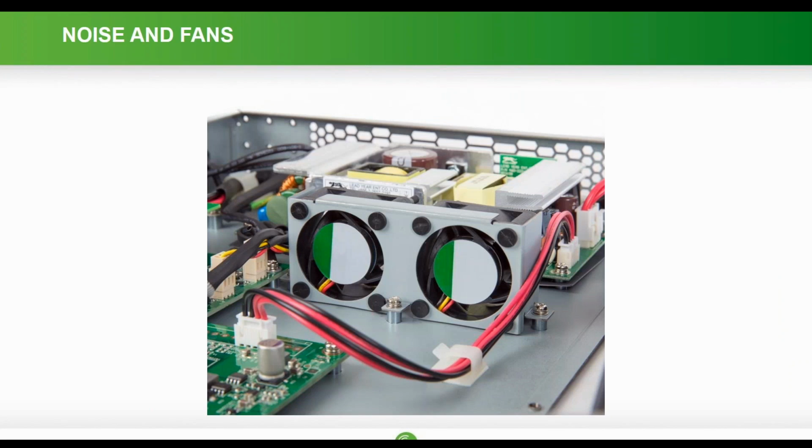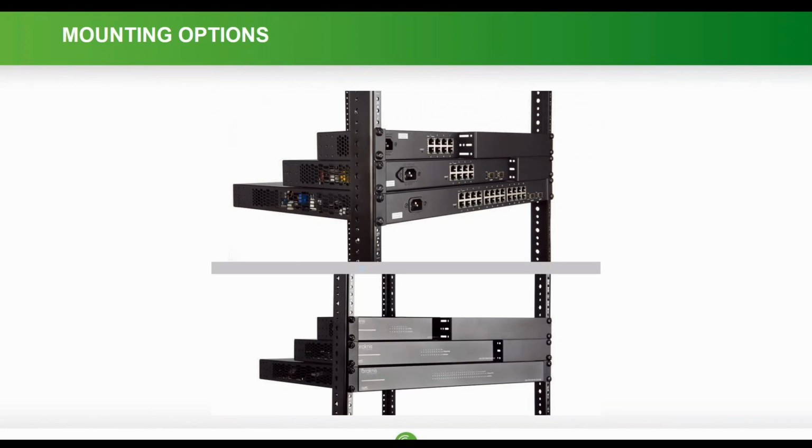The other thing you see in the PoE models is in terms of fans. For the 300 series, those were multiple or variable speed fans controlled by wattage, so how many watts the switch is supplying controls what speed the fans run. We recognize that this is not the most efficient way to do it, so with the new line of switches, we have temperature controlled speed fans. There's a thermal sensor in each switch that drives the speed of the fan. This way we're providing the optimal ventilation and heat dissipation for the switch, while keeping it variable and as quiet as possible.